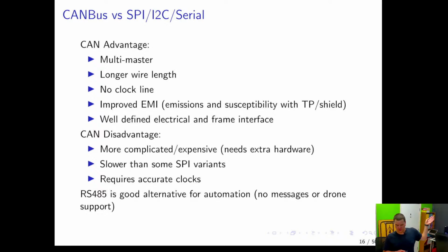The cooler thing about CAN compared to SPI and I2C is that you don't just get an electrical interface definition, there's also a data definition. With I2C and SPI, most devices use kind of the same settings, but the register maps are all different and the size of things is different. So if you're looking at the oscilloscope trace, you still have to merge numbers in your head. Everything shows up as bytes, so if it's a 16-bit register, you have to do this conversion yourself. CAN is just what it looks like every time, so you can just decode it.